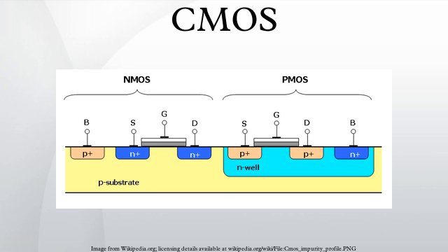The inputs to the NAND are in polysilicon. The CMOS transistors are formed by the intersection of the polysilicon and diffusion: N diffusion for the N device and P diffusion for the P device. The output is connected together in metal. Connections between metal and polysilicon or diffusion are made through contacts. The physical layout example matches the NAND logic circuit given in the previous example. The N device is manufactured on a P-type substrate while the P device is manufactured in an N-type well. A P-type substrate tap is connected to VSS and an N-type N-well tap is connected to VDD to prevent latch-up.